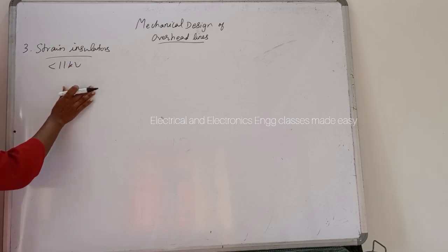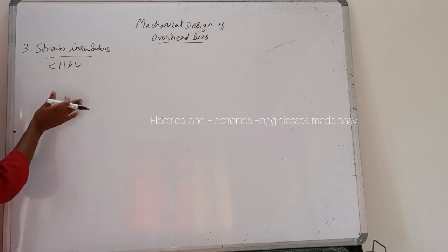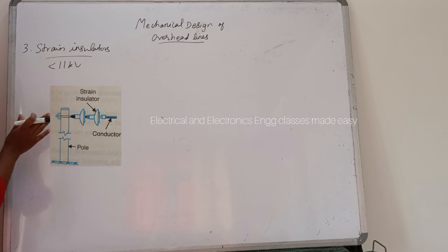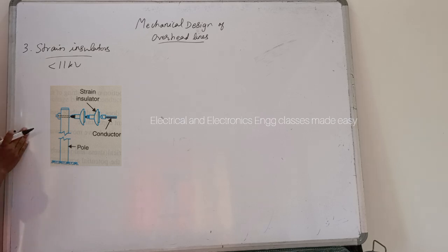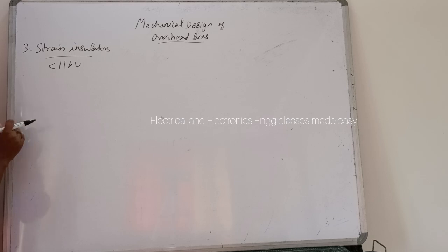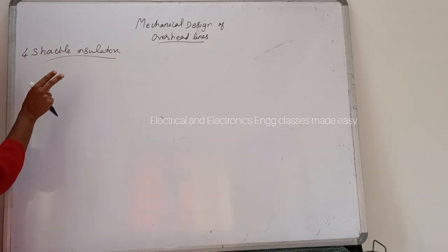However, for high voltage transmission lines, strain insulator consists of an assembly of suspension insulators like this. And the disc of strain insulators are used in the vertical plane. Or we can say the strain insulators are used horizontally. And when the tension in the lines is exceedingly high, as at long river spans, two or more strings are used in parallel. Next is shackle insulators.